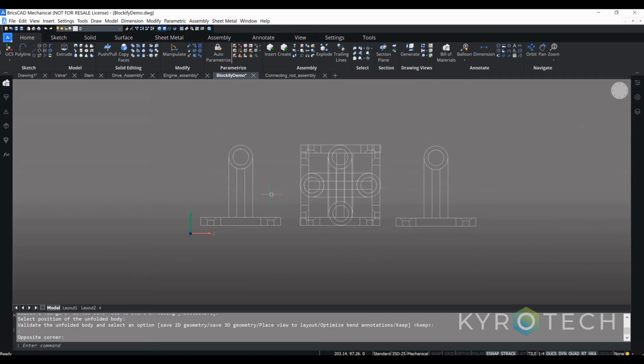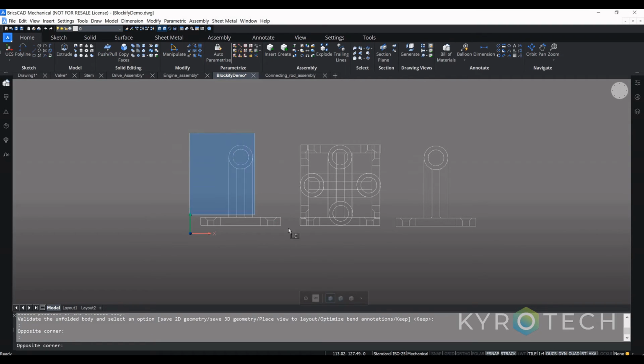But in BricsCAD, we have something known as Blockify. Now, what does Blockify do? It basically converts all similar geometry into blocks. If you can just see, everything over here is lines. It is an exported model. While designing, it has been done, and there are a lot of circles. So I'll just select this as a reference for the Blockify command.